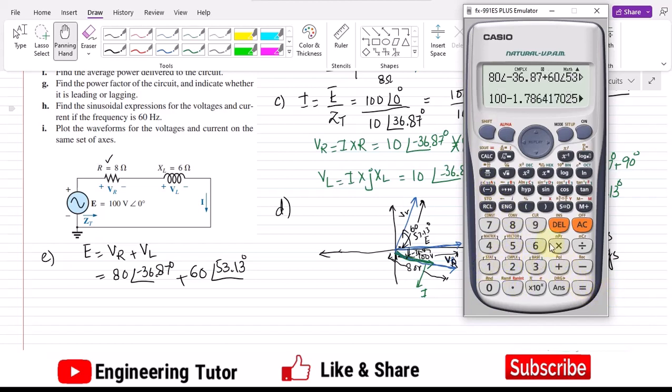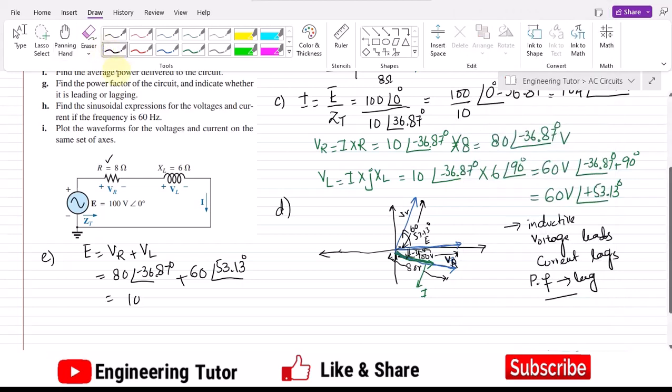Okay, so now adding them together, what will you get? You will get somehow like this, and that is almost, how much is it? That is 100, and the angle with it is almost 0 degrees. So that is the value of the voltage, which we may see is also here. So this implies that KVL is validated, and Kirchhoff's voltage law has been proved. Okay, so this is the solution of part E.